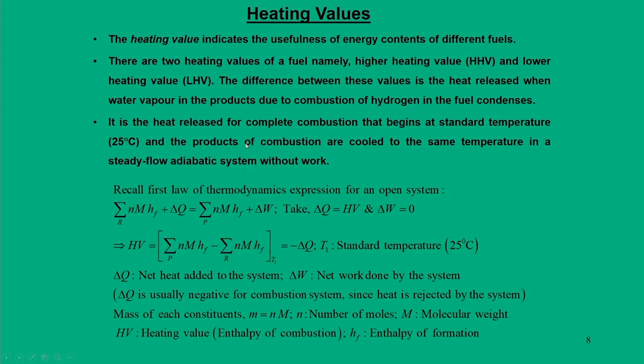So, basically we can recall the equations for an open system and set the term delta W as 0, that means no PdV work, and delta Q we call the heating value, that means the heat released during this combustion, and that is nothing but the difference between the total enthalpy of reactants and products. So, the heating value of the fuel is the negative sign of delta Q, which is nothing but the negative of heat of combustion.